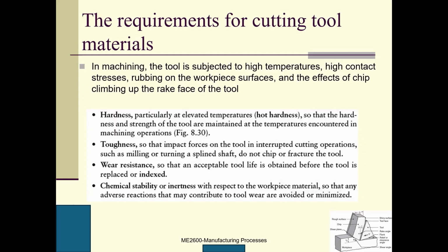Sometimes the material is very, very strong, but very, very brittle. If there is any impact, it breaks. So that's still bad, right? The third one is wear resistance, so that an acceptable tool life is retained before the tool is replaced or indexed. Indexed means that if this insert is worn out, you can automatically change to another insert. So this is wear resistance.